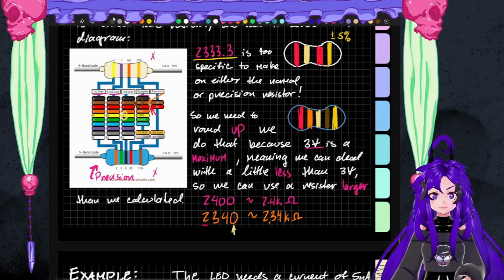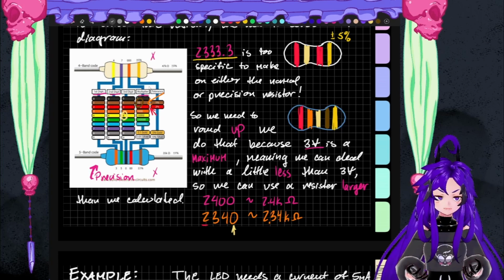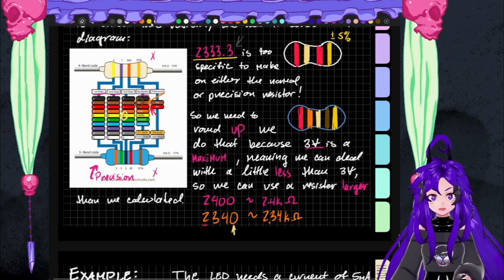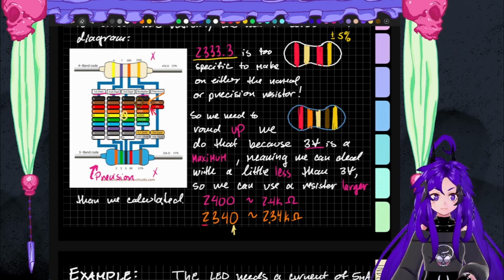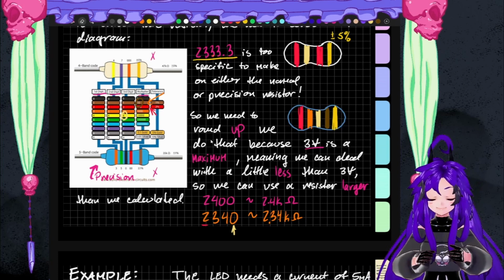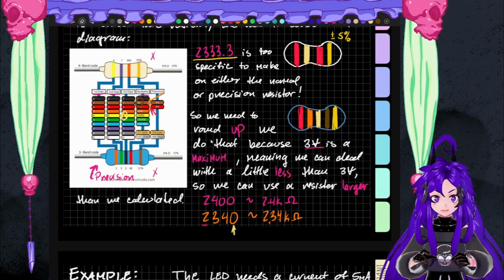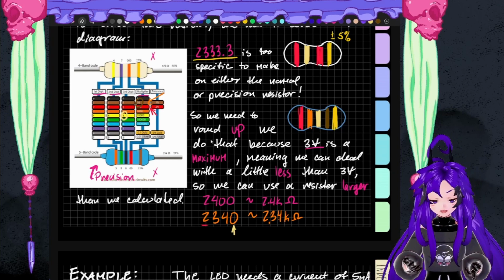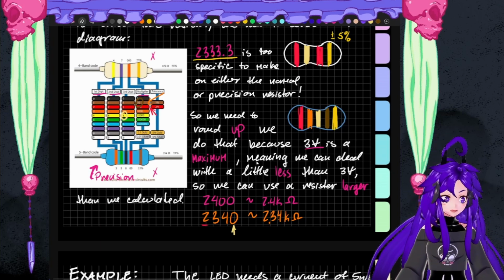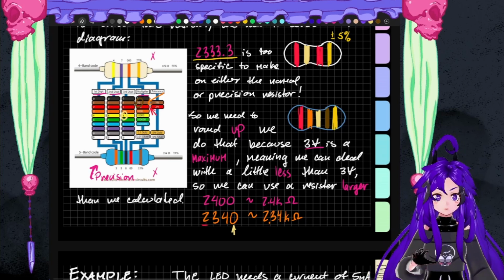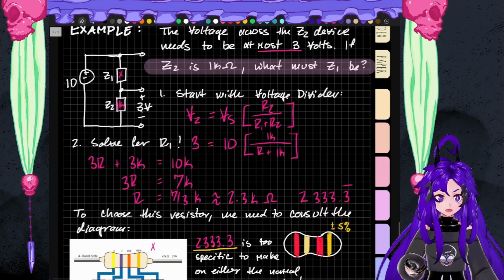More than likely, you're just going to have a vat of resistors, and you're going to pick something that is the closest to this without going under. Unless you were given that it has to be at minimum this, in which case you have to make that voltage at minimum for the device to function. Some devices are like this. Looking at you, tower servos. Also LEDs. But anyway, this is how you would go about figuring out which actual resistor to plug into your circuit here.